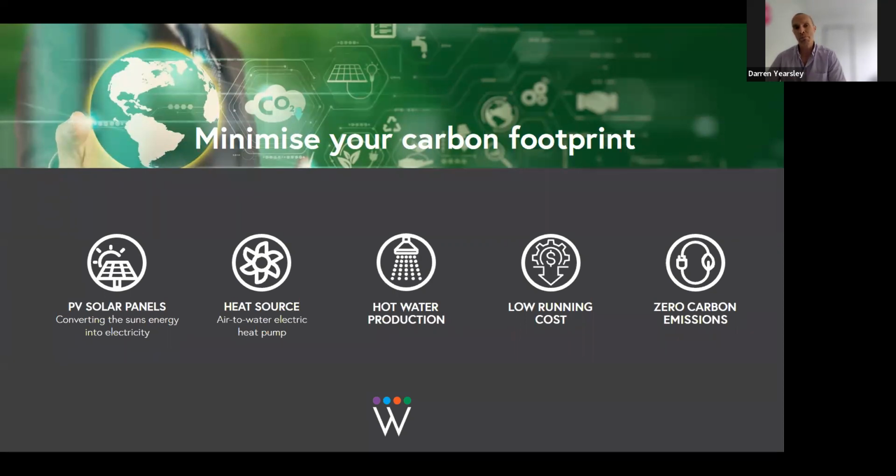If we put a solar PV array on the roof, every kilowatt of electricity which we produce with that system, we're levering at a rate of 3:1. So we supply 1 kilowatt of electricity to the heat pump, and it gives us back 3 kilowatts worth of hot water. Now what that does is it really drives quite a strong capital efficiency.